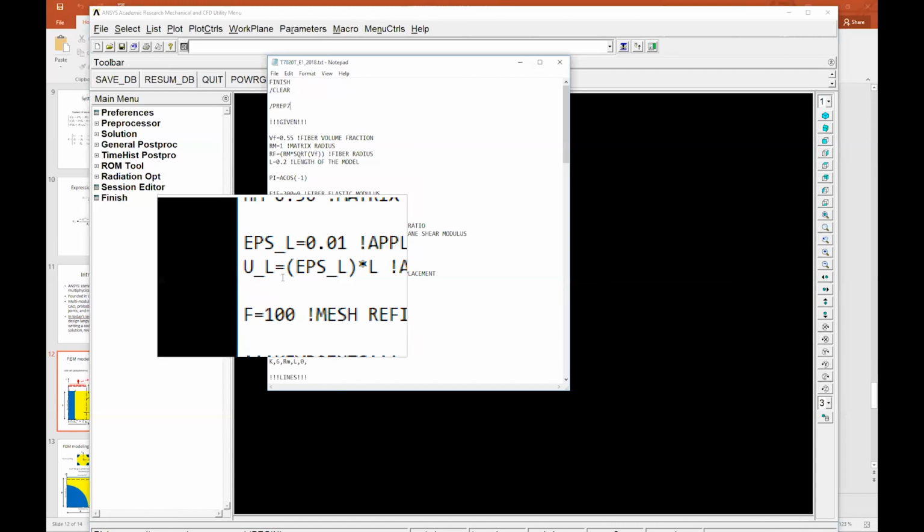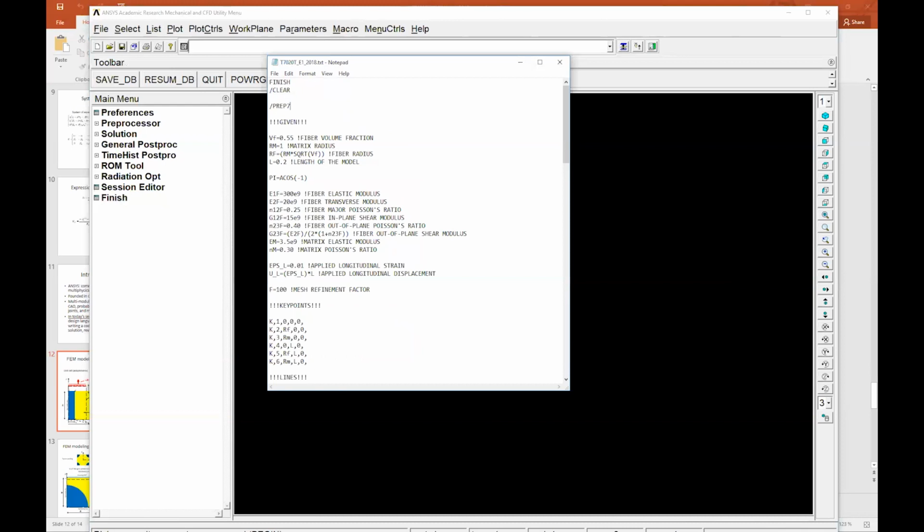And well, I can tell right away that if you remember the lecture, we had a small talk regarding convergence analysis, right? That when you create a finite element model, you don't know exactly how much you should refine the mesh. Is it going to be accurate already, or is it maybe inaccurate? So for that, you need to parametrically control the size of the mesh, and we will do that with the help of this mesh refinement factor, as you will see later on.